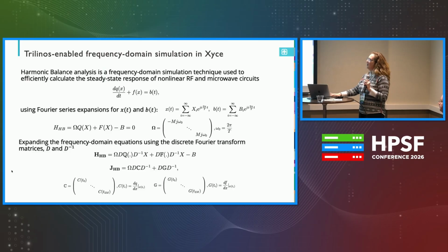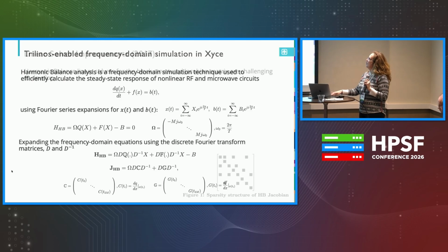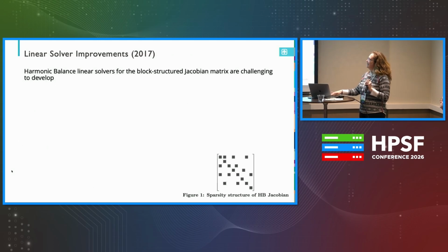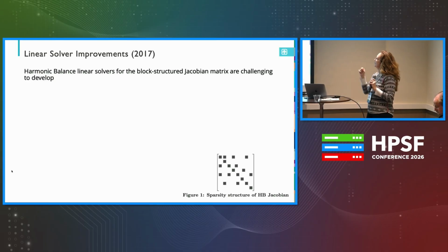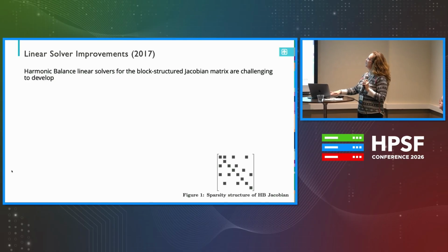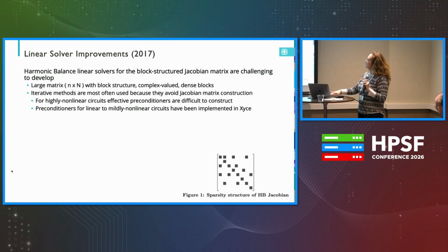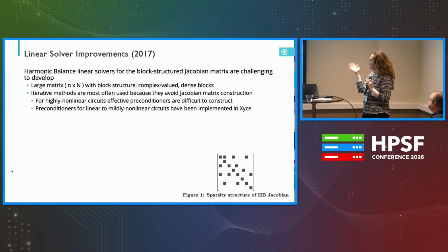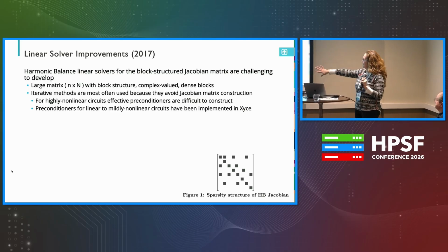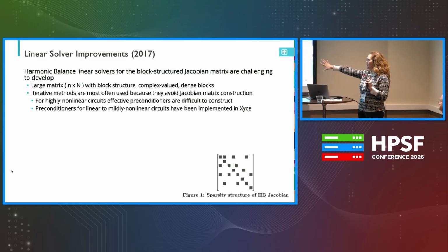And most people don't want to solve it. In general, they like to use iterative approaches and maybe a block Jacobian. But we actually leveraged a Kokkos solver, the Basker templated solver, to create a direct solve, which was developed using this sparsity structure. What you do is you take the original sparsity structure of the Jacobian, and each entry is now a block.